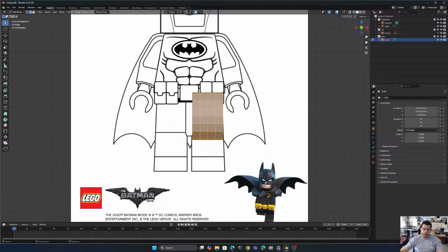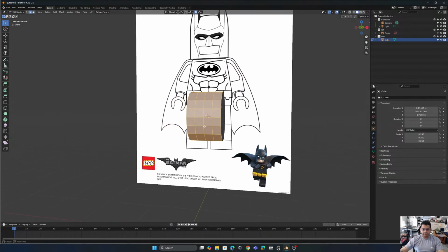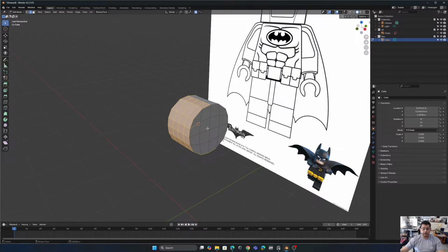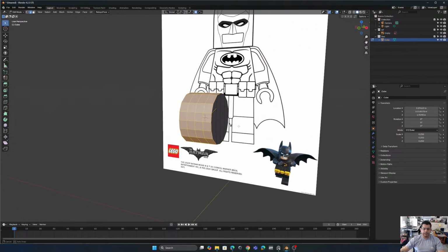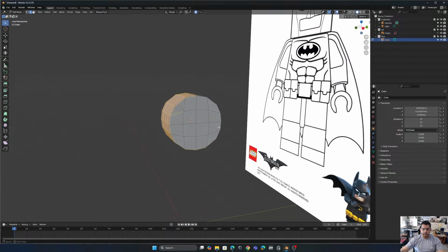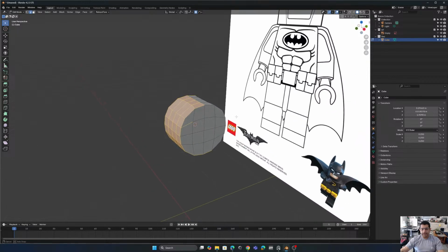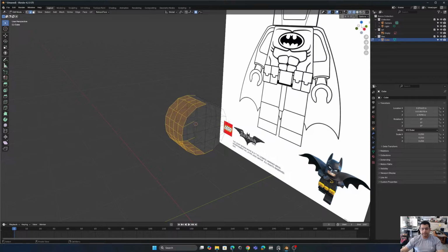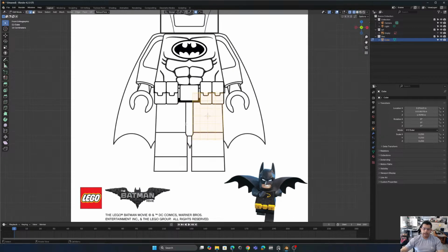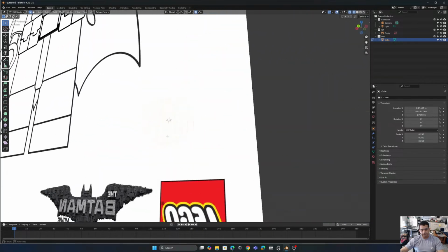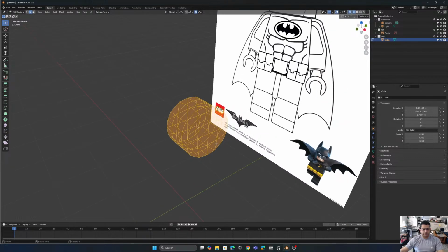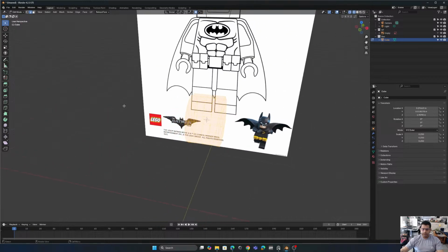If you only work in this view, when it's completely gray, and you select using the front view, you're only going to select the faces that you can see from that side. If you want to select something that is in the back, you have to press Shift Z, press 1, and then drag your click, and you could select everything. As you can see, it's really useful because you could actually see through the geometry and also select everything that is in the geometry.